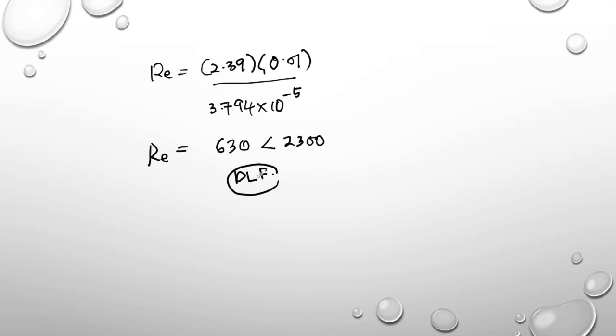You know that if we are assuming that this is fully developed laminar flow, it has a constant value of Nusselt number equivalent to 3.66. Therefore, we do not want to assume directly that this is the region where fully developed laminar flow occurs.